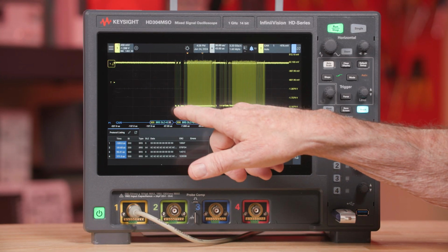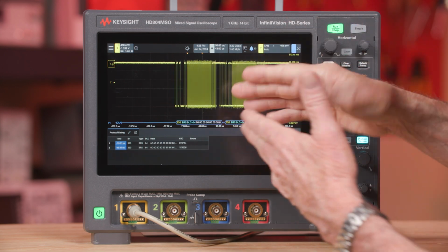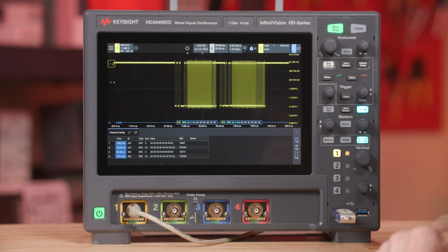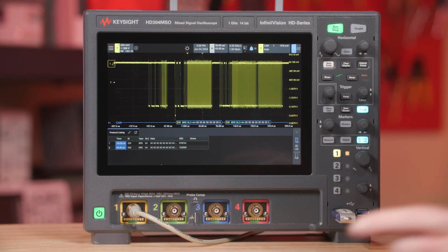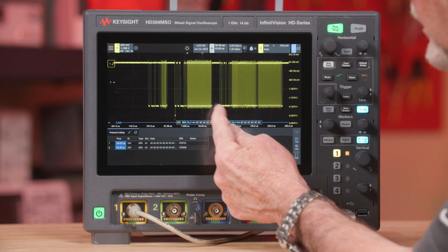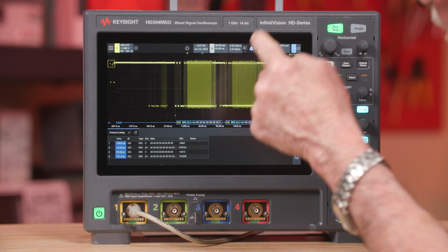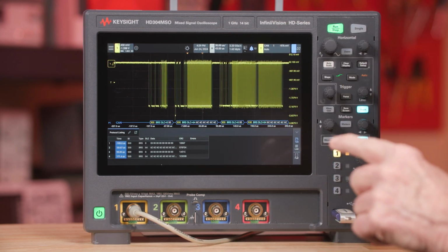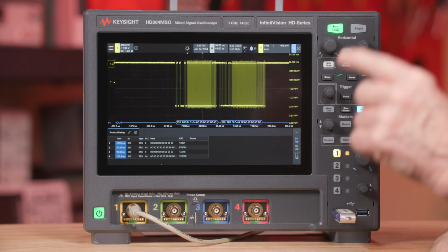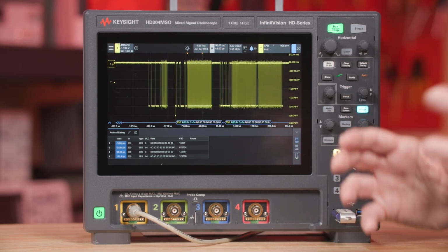Here you can see the arbitration field, which in this case is being transmitted at 500 kilobits per second, followed by the data phase, in this case 64 bytes transmitted at 8 megabits per second. So you can pack more data into a single frame running at a faster rate to reduce overall bus load.